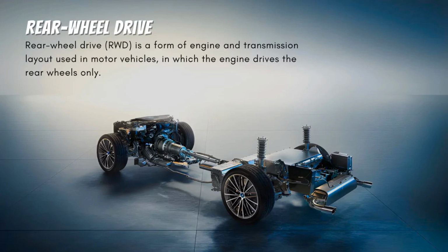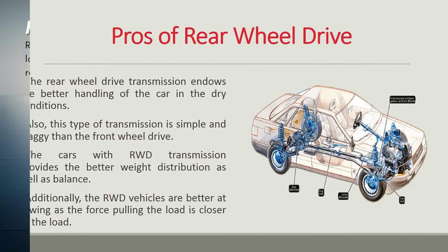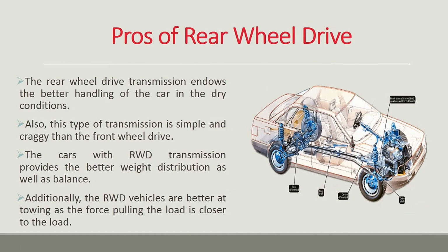Options for connecting the locks largely determine the type of all-wheel drive. Locking can be carried out by a lever from the cabin or by pressing a button, after which the servo drive will carry out all the necessary manipulations. Modern cars are equipped with different types of self-locking differentials. It is the degree of locking and the difference in the torque transferred will determine the nature of the behavior of a car with all-wheel drive.